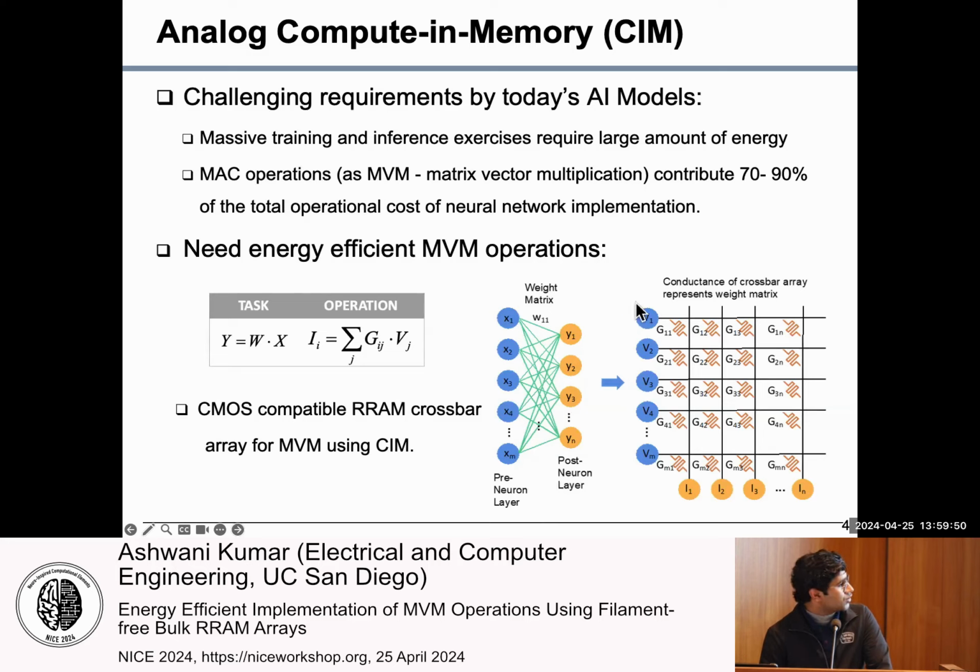So this architecture you can directly transfer on a crossbar architecture, where you can feed your input and implement your complete weight matrix on the cross points, which are two-terminal memory devices. Your weight values can be translated into the conductances of these memory devices. The current flowing on the horizontal line is the multiplication operation, and you can sum up those currents in a parallel fashion on the vertical lines. So that's how simple it could be.